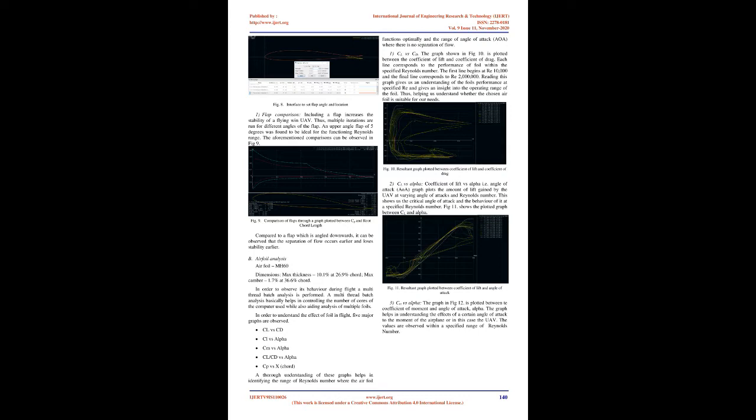Now, in an aerial vehicle the balancing of weights is crucial. Thus, the positioning of the mentioned components is dependent upon the COG. The COG determines a plane's static and dynamic stability. Initially the components are placed randomly, and a rough length of the root chord is found. The final length falls within the initial length as it depends upon the dimensions of the components themselves.